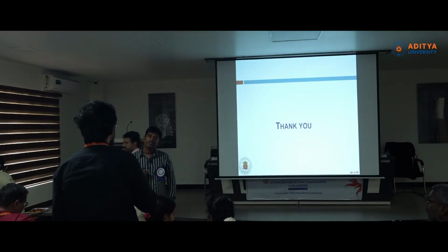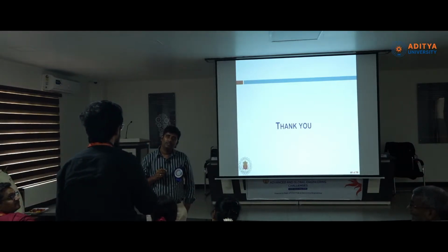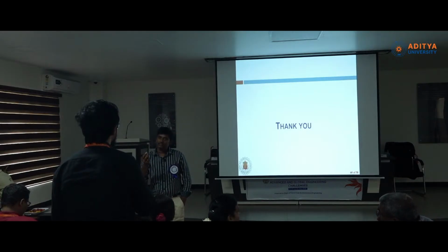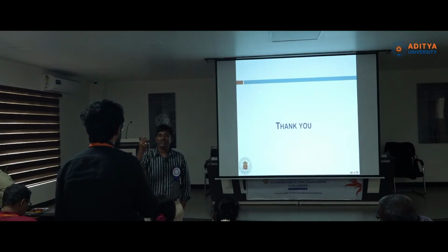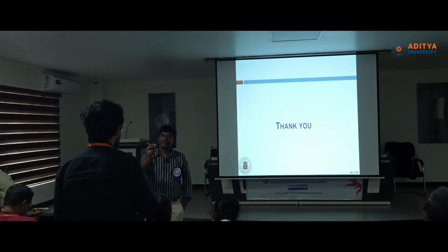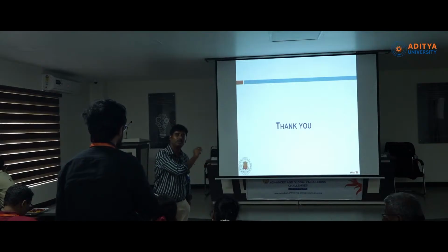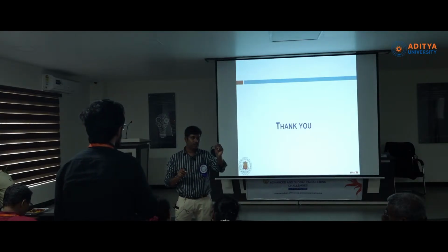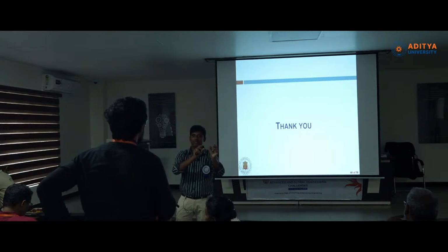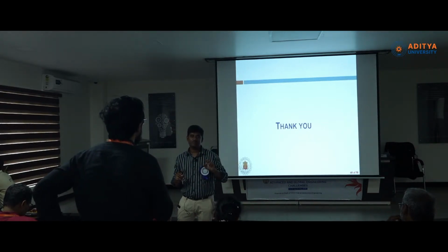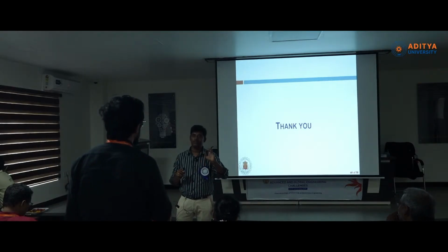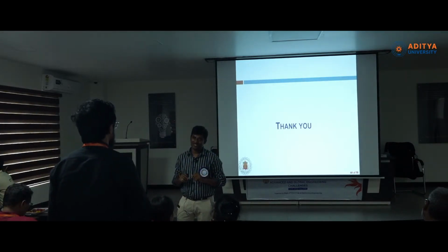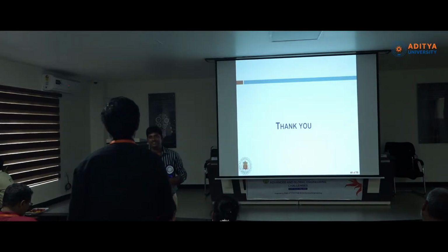Thank you, sir. Second one, how do we distinguish between quantified and non-quantified parameters? You said a few we have to take as quantified. Yes, in your PhD work you also mention this. I told you, electrode size can be quantified, but electrode shape cannot be quantified. Like a triangle electrode and a square electrode, how can you distinguish between them in a numerical study? In a numerical study, I will tell you how size affects it. If you increase the size of the electrode, the discharge gap reduces, and one of the input parameters I have taken is the discharge gap. So if size increases, the discharge gap reduces, and that way it can be quantified. If you change the shape, you cannot estimate the discharge gap. That is the thing. So practically you need to think like that, you can understand. Thanks. Welcome.